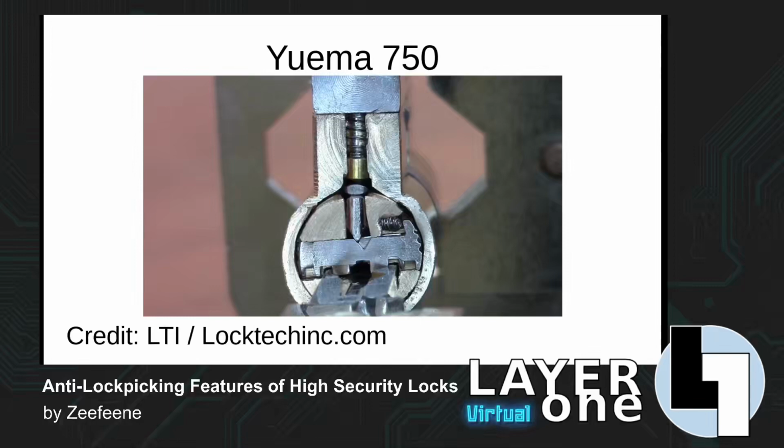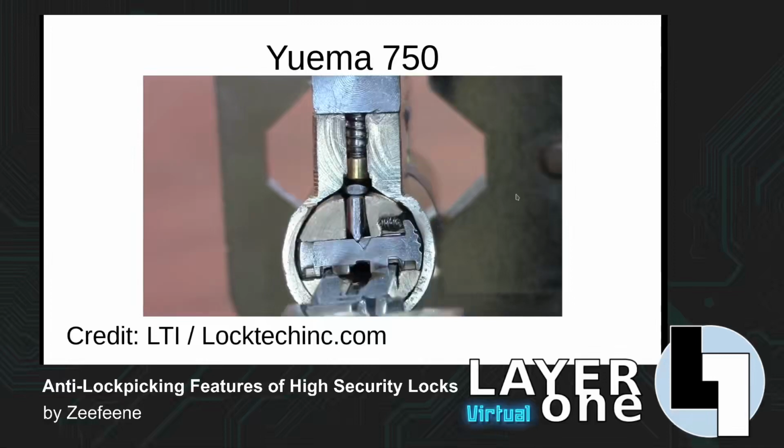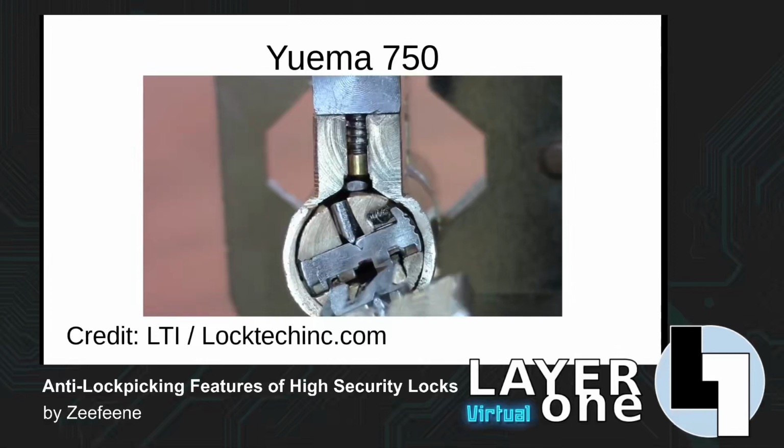So here we can see the lock with an incorrect key inserted, and we can see that we have these silver sliders which have this V-shaped cut in them, here not correctly aligned. We have this lower portion of the reverse sidebar, and we have this little upper portion of the reverse sidebar that is sitting above the shear line outside the outer circumference of that plug. And so when we turn the plug with the wrong key inserted, well, nothing happens, essentially.